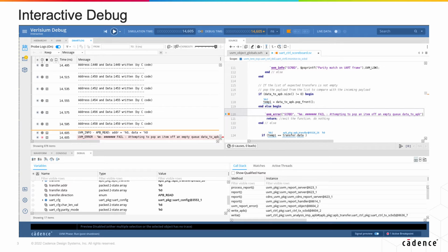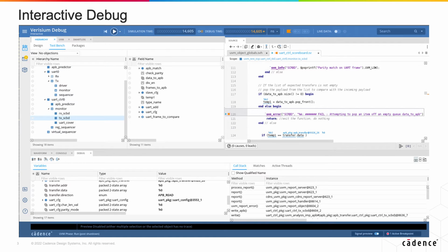We can see all the global and local variables of the scope, and we see the stack at the lower right-hand side. I could press on this hierarchy to get connected to the full hierarchy tree and see the instance in my full UVM hierarchy and understand the agents, monitors, drivers, and sequencers in my hierarchy, as well as dynamic objects in the variable screen.